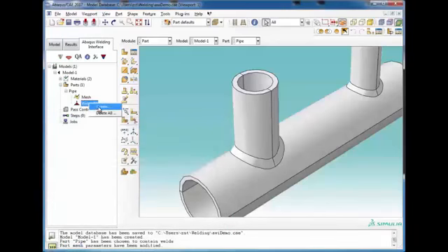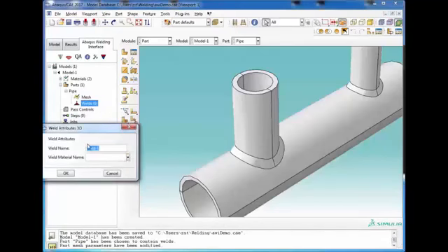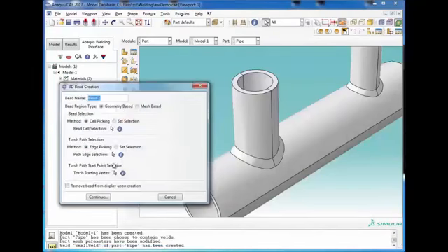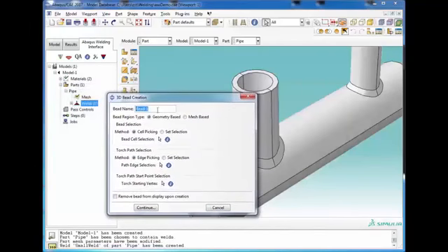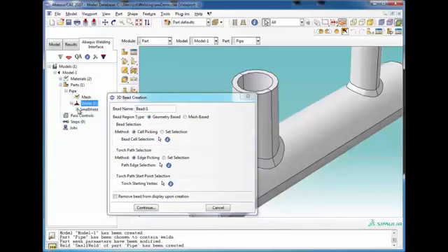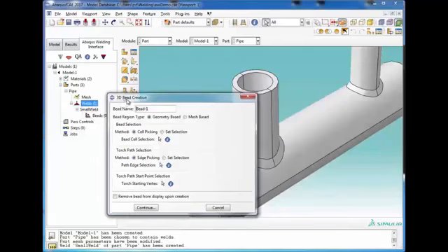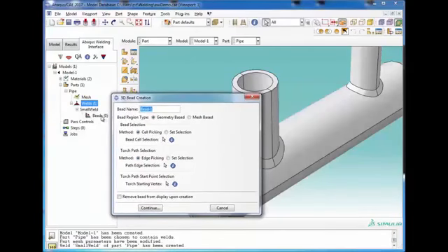Okay, so the next step is to actually define the welds. We'll start with a small weld, give it a name, give it the material, and then you'll see the bead selection pops up automatically. Now if you look at this weld repository, we have the small weld, with beads displaying as 0 beads have been selected. So that's what this dialog does.